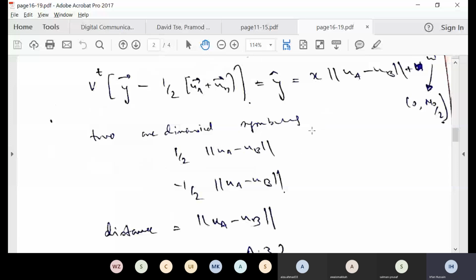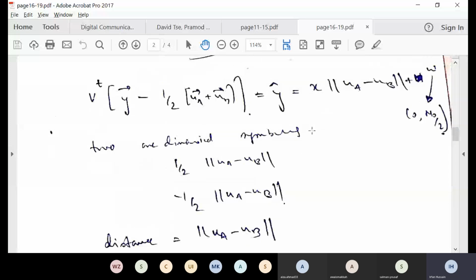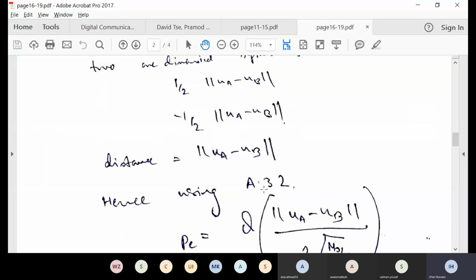So what is the signal-to-noise ratio? Use the previous scalar problem, where the probability of error between two scalars depended just on the distance between them, and the distance between these two scalars is this minus this, which is actually this. So this is the error. This is the intuition. Based on intuition, you have just developed a solution which is actually proving our previous result.